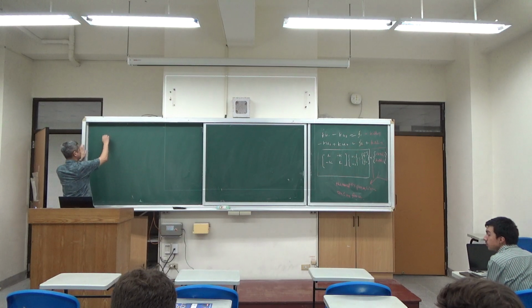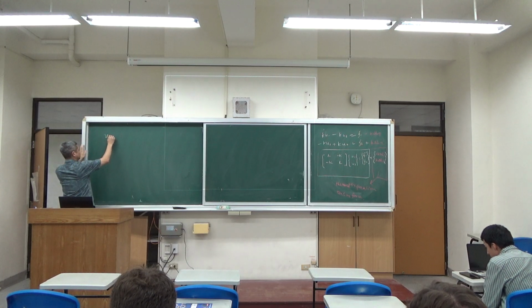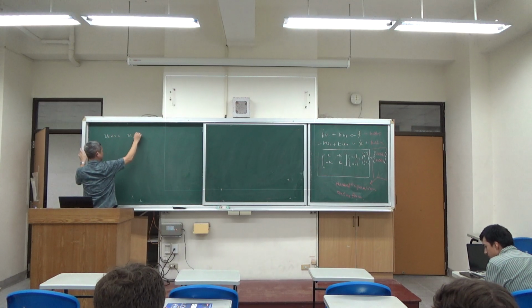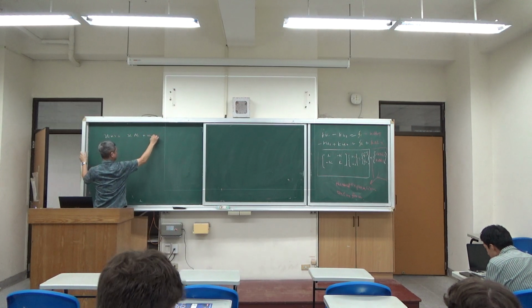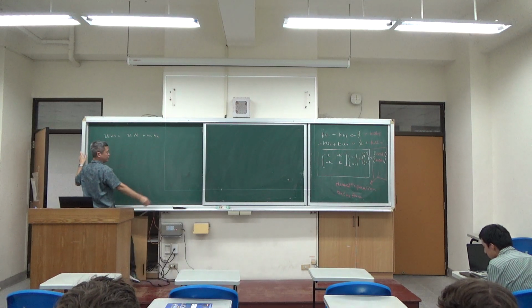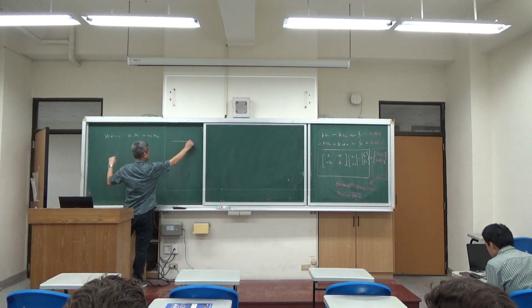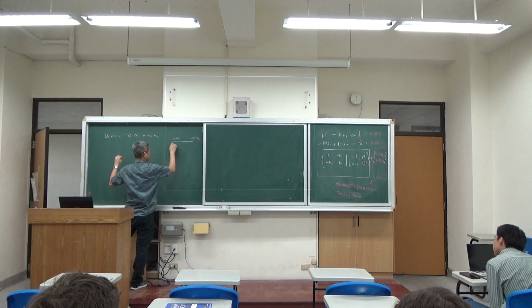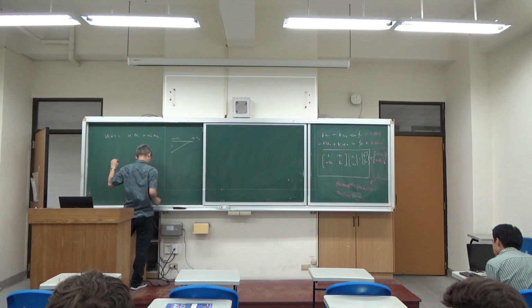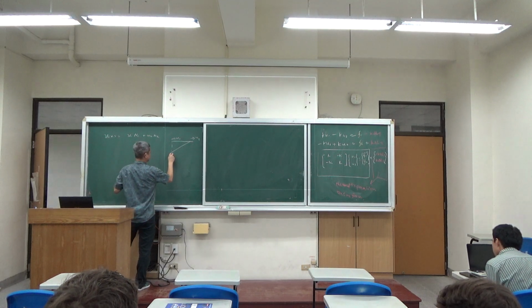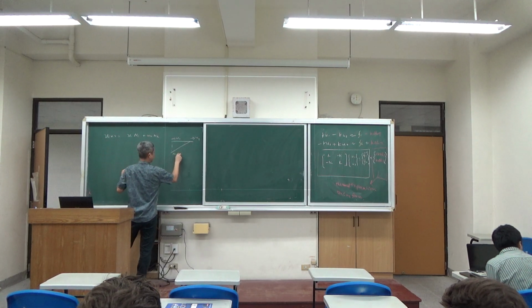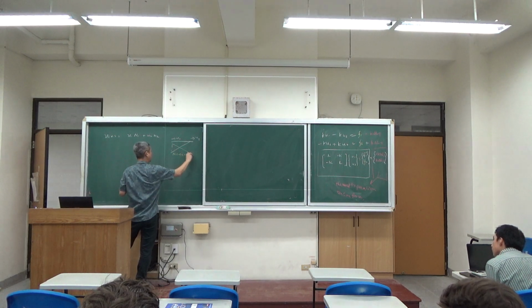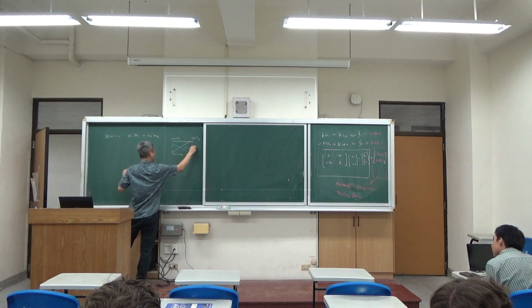The displacement at any point is equal to u1 N1 plus u2 N2, where u1 and u2 are interpolated by two different shape functions. N1(x) is equal to 1 minus x over L. The other, N2, is equal to x over L.